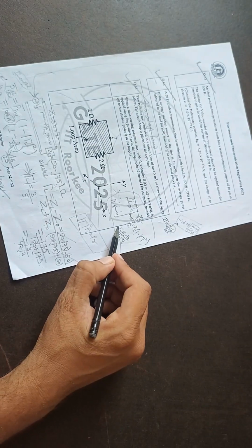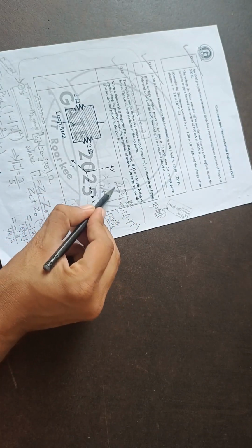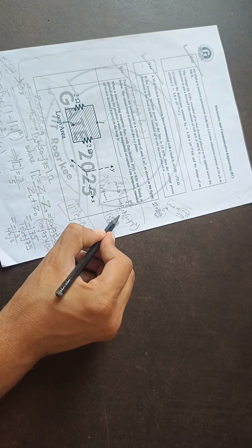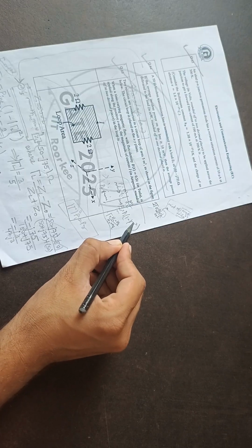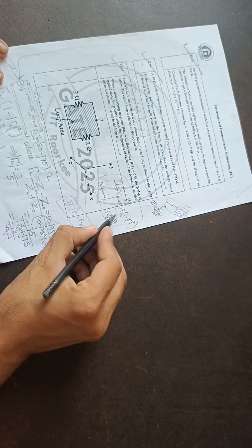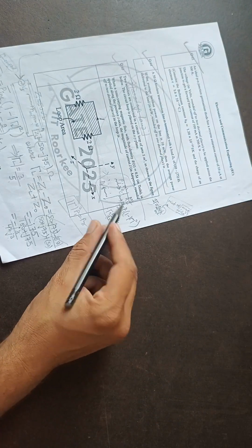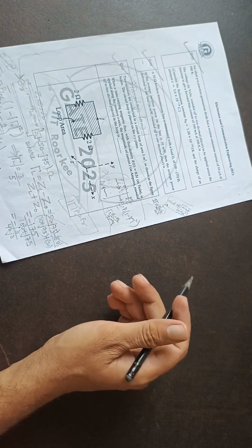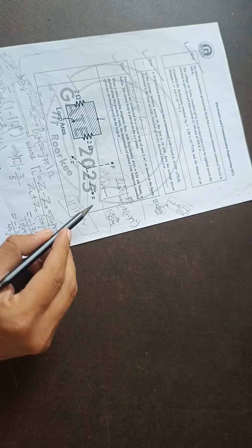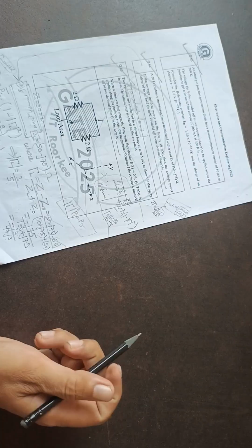A similar concept is also used for normal incidence in plane waves. If the incident power from medium 1 is Pi and the reflected power is Pr, then the transmitted power is Pi times 1 minus gamma squared. Again the reflection coefficient is (eta 2 minus eta 1) over (eta 2 plus eta 1), where eta is the intrinsic impedance of medium 1 and 2. So a similar concept is used in plane waves also. The reflected power is the reflection coefficient squared times the incident power.